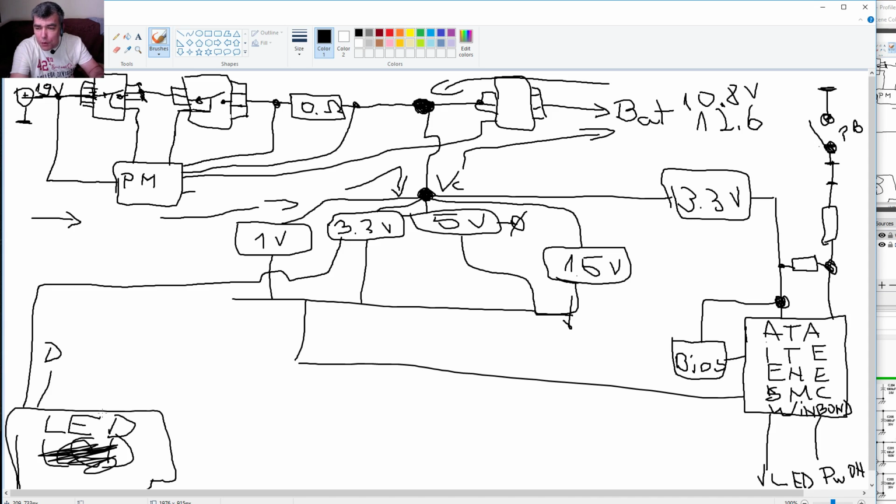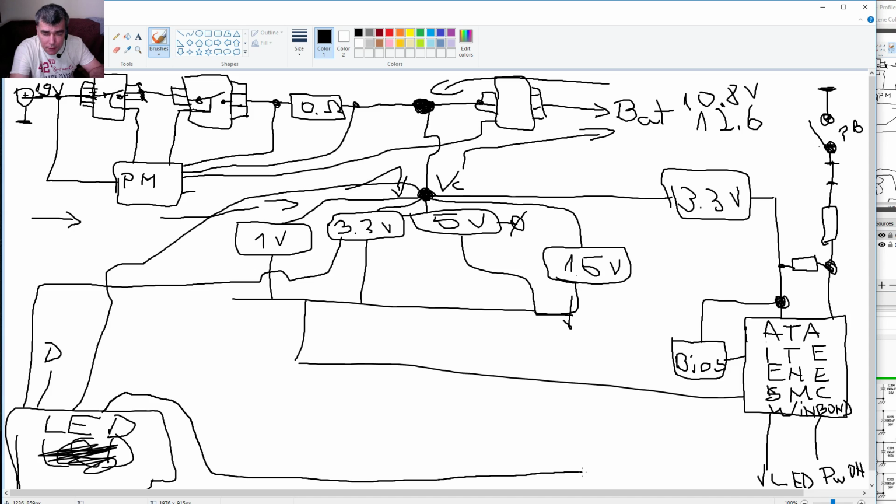Yeah, that's what we have to check if you don't have picture, but you have light. On the light side, you have 19, which is coming from here, same point, yeah. We have these pins, you see these ones, which are coming from this chip. That's the thing. And we have one more pin. Sorry, I'm not going on drawing. From here, yeah.